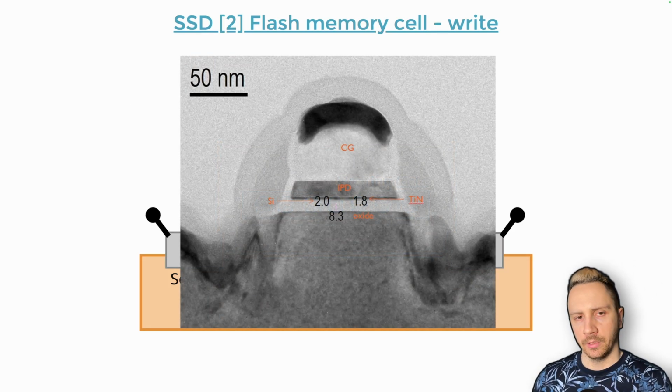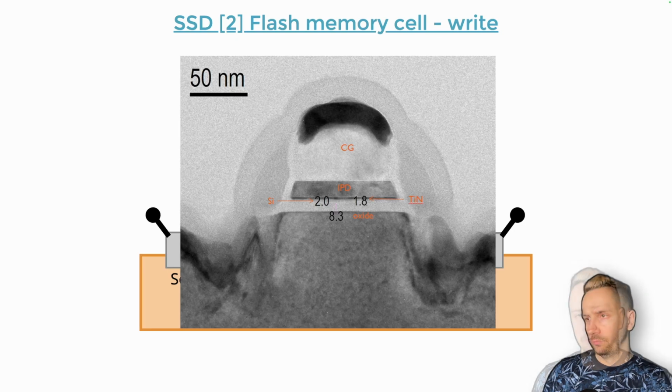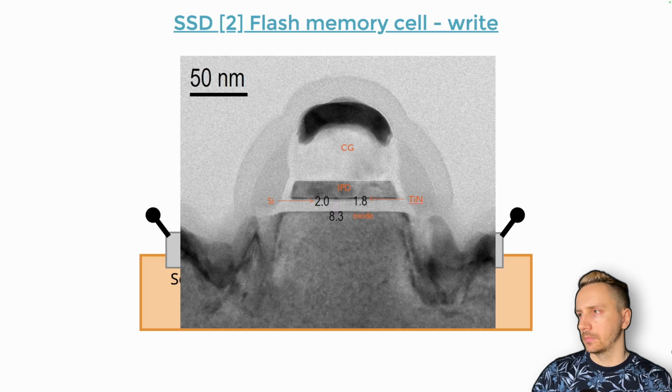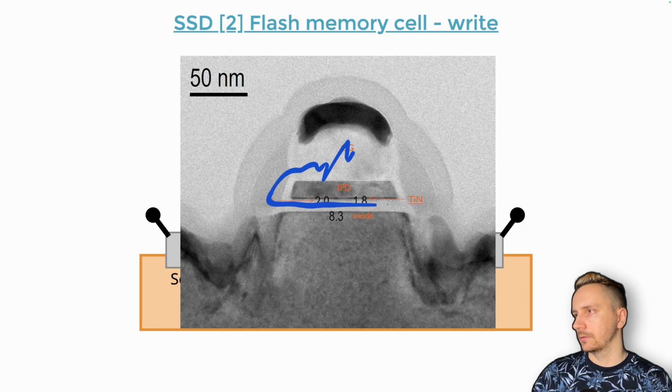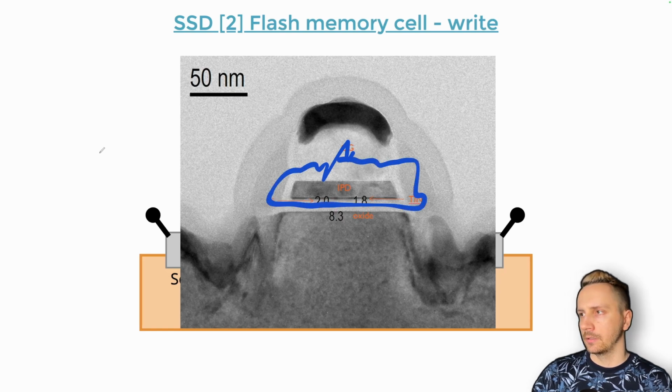There is a microscopic photo of one bit which has all those things that we just saw. This platform is a floating gate. This thing here is source, this is drain, this is control gate. This floating gate is trapped inside a thick dielectric layer, where electricity cannot go.